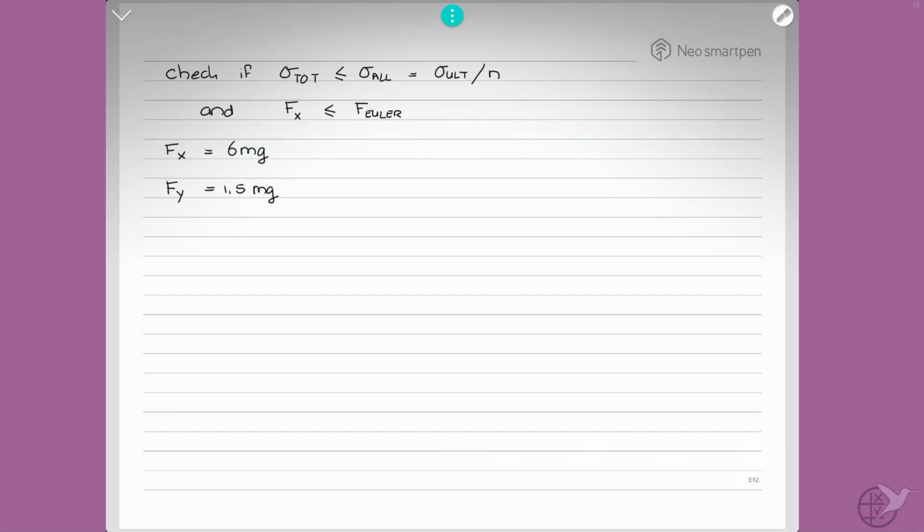So if we then start calculating sigma x and sigma y that make up sigma total, we get that sigma total is equal to sigma x plus sigma y is equal to Fx over A plus Fy times L, that's the moment the lateral forces cause around the base, times the place where this occurs on the outside of the cylinder, so R, over its area moment of inertia.